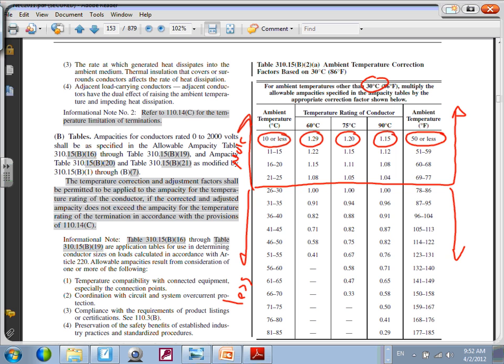I don't know of any engineer who uses the more. Usually either less or stick with this. Here's the cutoff. This is the typical. See 111 at 30. At this range, you don't add or subtract, right? So 100 amp, if I put 100 amp in a place with ambient temperature 78 to 86, like in Minnesota, for the most part, I don't add or delete.